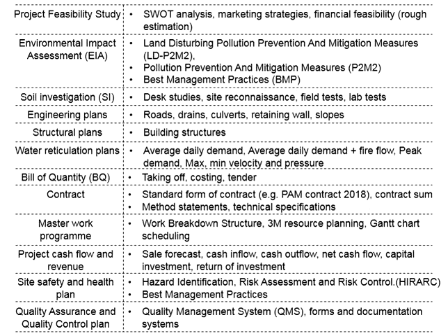These are the measures to minimize the impacts related with the work activities that can disturb the land, such as earthwork, excavations, site clearings, and so on. As a result of these land disturbing activities, there can be air pollution, erosions, slope failures, and so on. You will need to prevent all the adverse impact associated to the land disturbing activities due to the project.